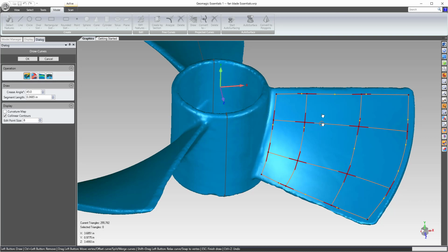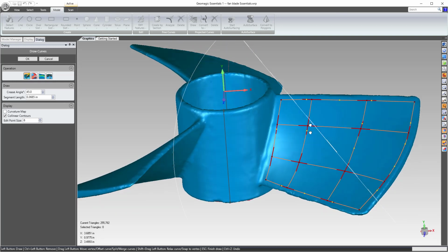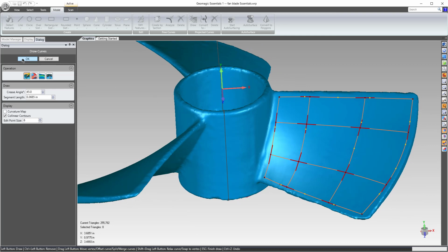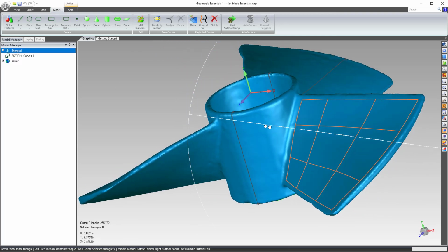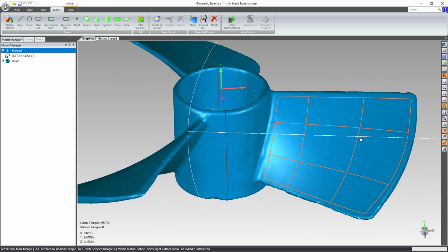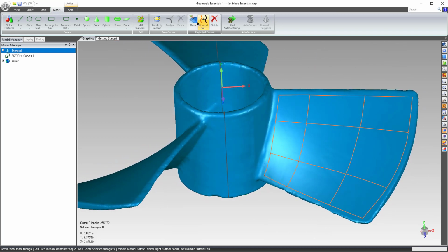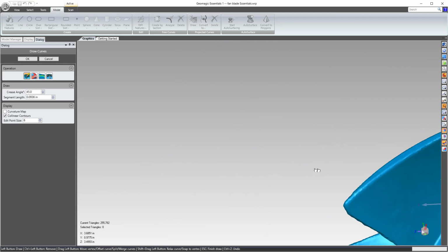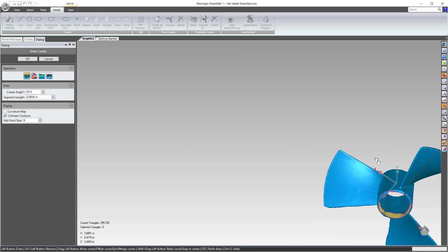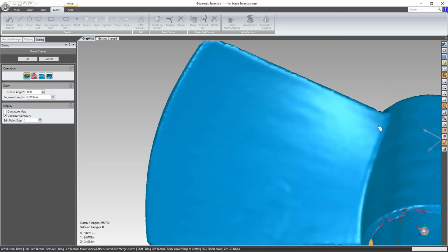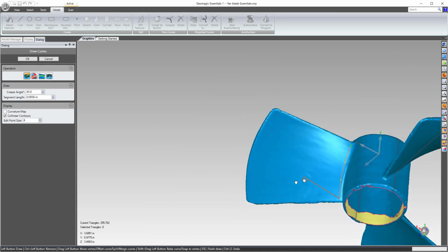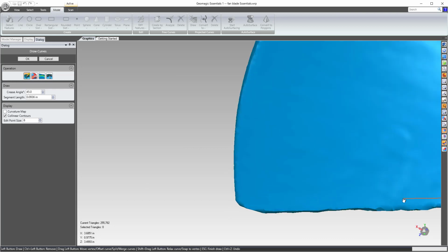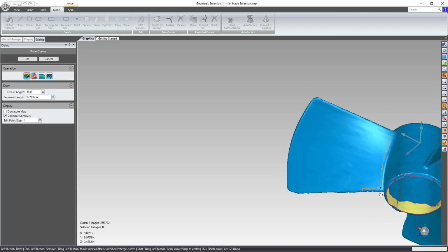So these are just to give me enough resolution to draw them inside of Solid Edge or convert them inside of Solid Edge. So you can see that I went ahead and I selected those curves and I drew them. Now, actually, let's go in and draw them on the other side because this isn't necessarily a constant thickness blade. If it was, I would just draw one side and offset the surface that I use, which many of the companies that make these, they all know when they're designing it whether it's supposed to be an offset or a constant thickness blade.